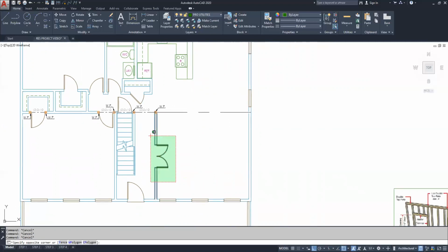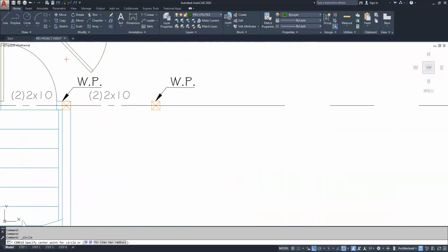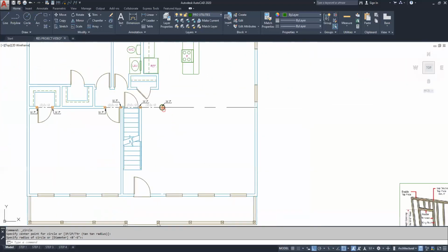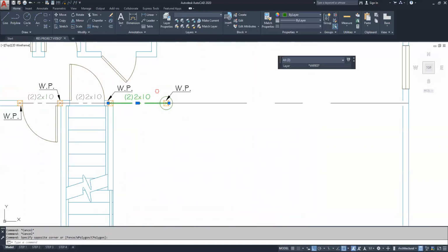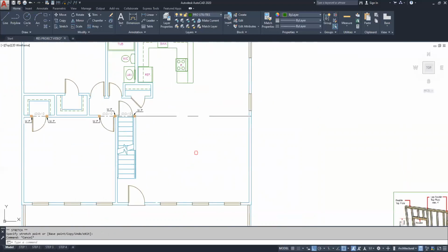This wall would not be as difficult. This is not a bearing wall. So if I want to erase that one, that's a lot easier. But then I have to make sure that this post is still going to be here. If I decide I don't like this post, I can get rid of that post and then bring this header to here. But then guess what?